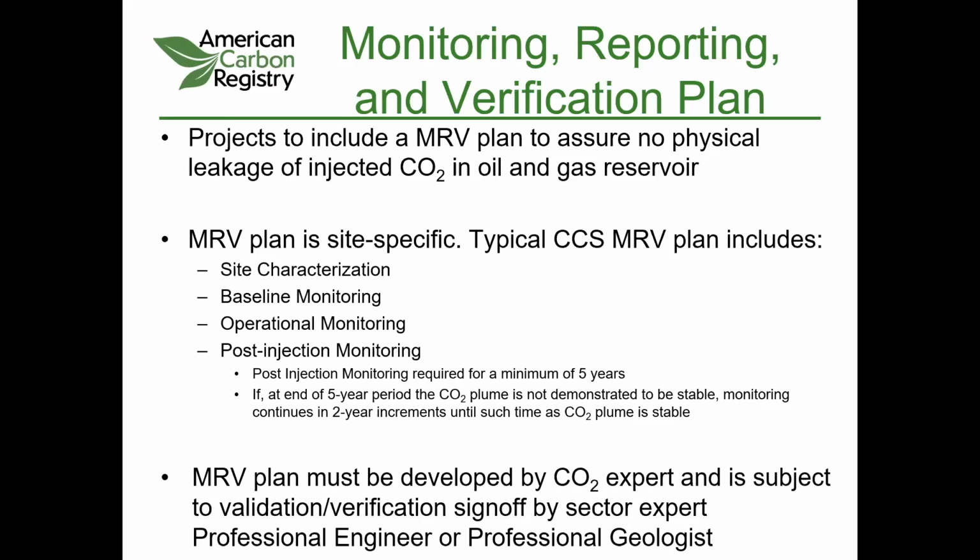we would be monitoring. And then there's that post-injection monitoring, which we have now as a minimum of 5 years. And if we can't ensure plume stabilization at the end of that 5 years, we would increase it in 2-year increments until we can demonstrate that that CO2 plume is stable, that it's behaving as was modeled in the site characterization.